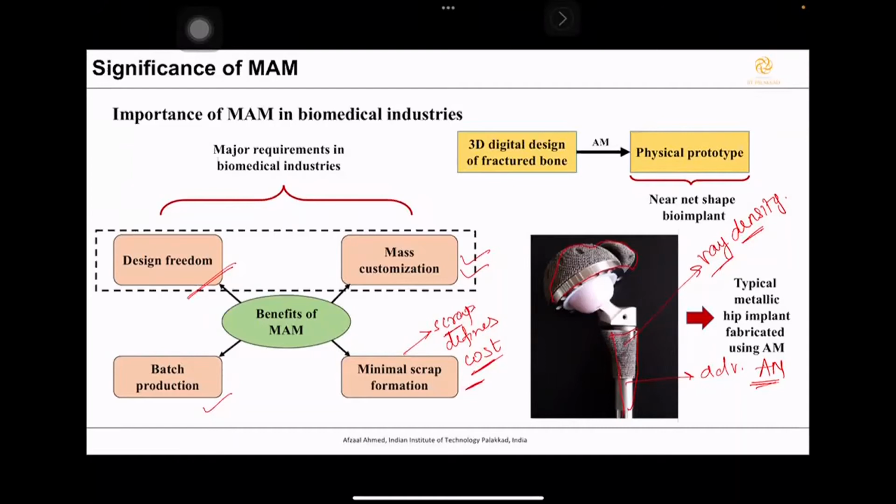Is this the same case when using the chemical etching method also, sir? In the literature review which I was doing, the chemical etching method was used only once previously. Does the dimensional accuracy problem also come with the chemical etching process? Definitely. Chemicals are very hard to control because they do selective etching. If you see titanium alloy Ti-6Al-4V, there are three components: titanium, aluminum, and vanadium, and they selectively etch all these components.